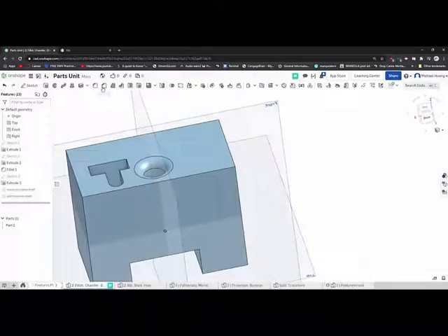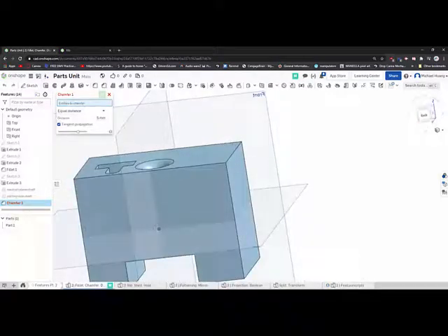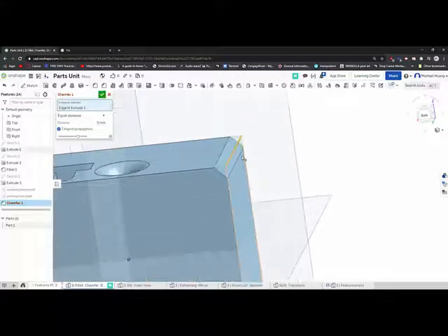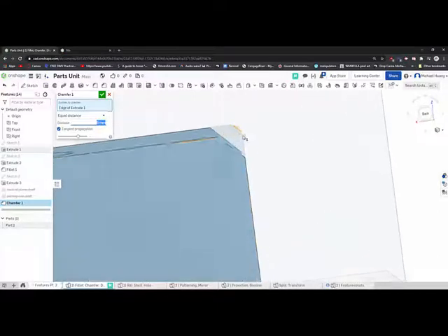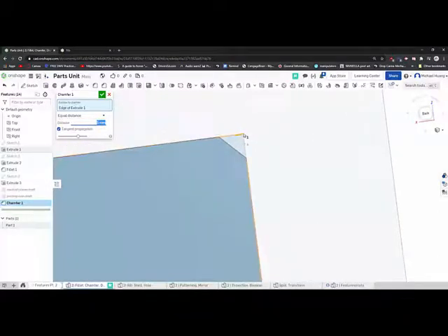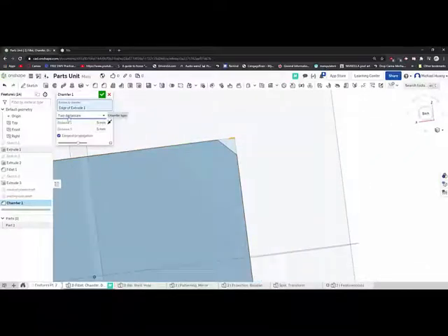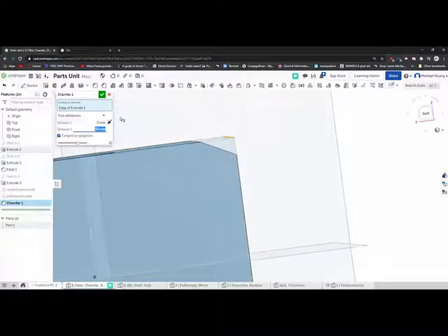Next is your chamfer. Now chamfer is relatively simple. You can click on the edge just like with your fillet, and it's actually going to cut that edge. All right. And I have an equal distance chamfer here, so it's going to be 5 millimeters to the left, and then 5 millimeters down. Two distances is going to allow me to cut in two distances. So you'll see it's 5 millimeters down, and then 10 millimeters to your left, and then you can change the direction.